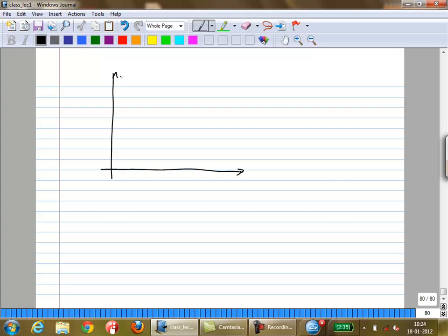So for a MOSFET, if you plot the total IN squared, the total current noise, as a function of frequency, what is it going to look like? Let's say you plot it in log scale. You're going to have something like this. This is thermal noise.